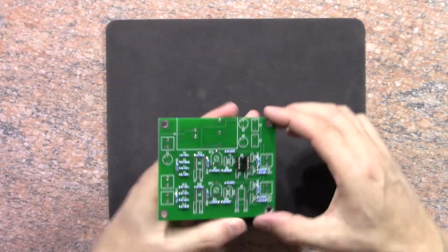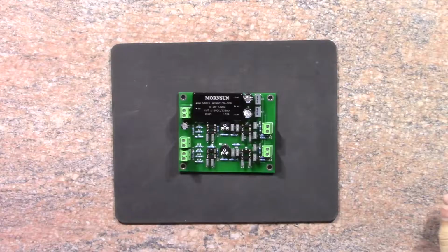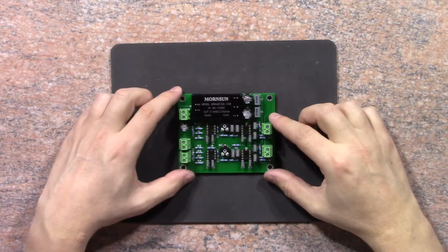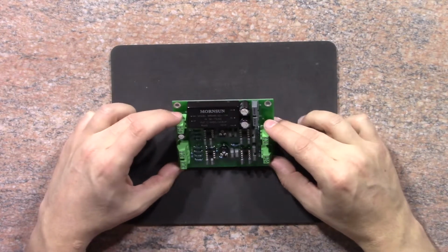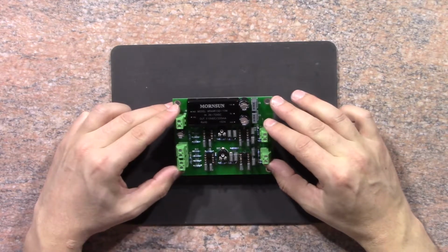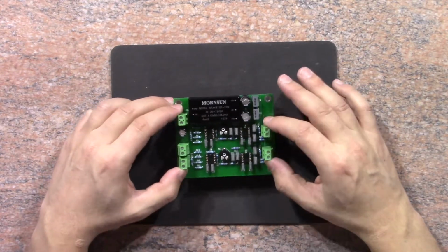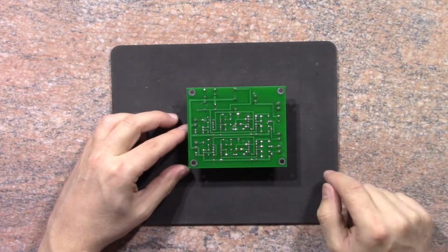And that's it. The first IC socket soldered in. So all the components have been soldered onto the preamplifier card now. And at this point it's best to take a 5-minute break, come back and just make sure you've put all the components in the correct place and that all the components are the right way around. You can also see the soldering left a flux residue on the back of the card.